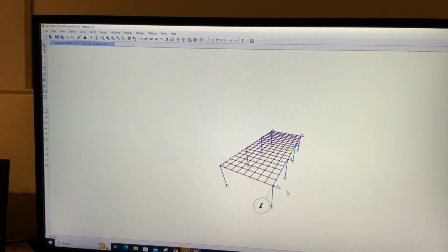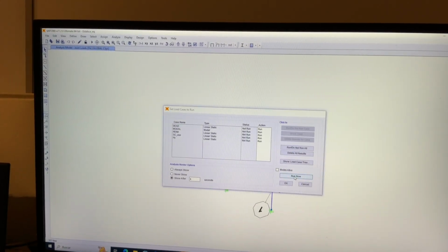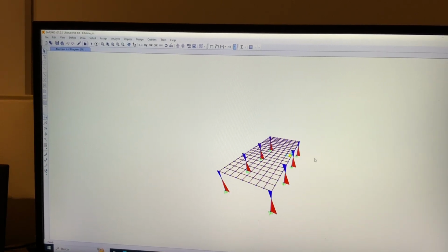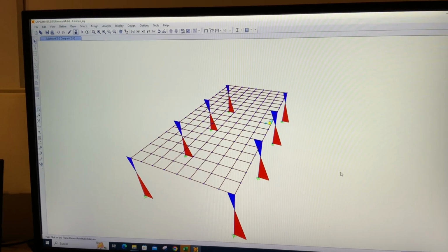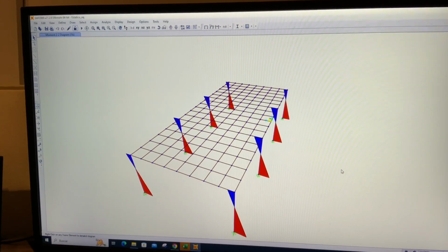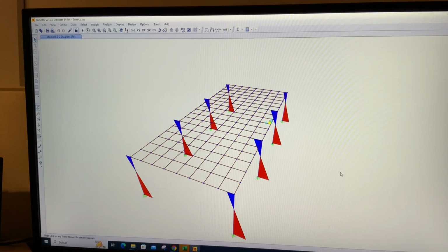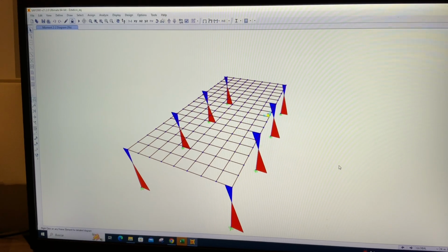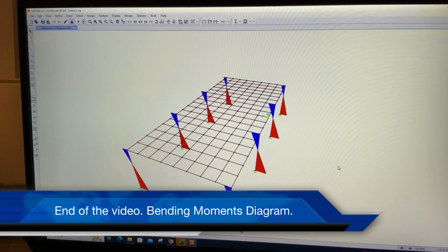If we now perform the structural analysis, and pay attention to the RC columns and request the bending moments from the program, you will find these diagrams. They are typical when you have a great amount of lateral horizontal forces. The bending moment is only due to the seismic forces, so there is no combination with other loads.